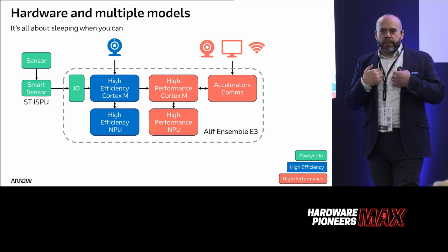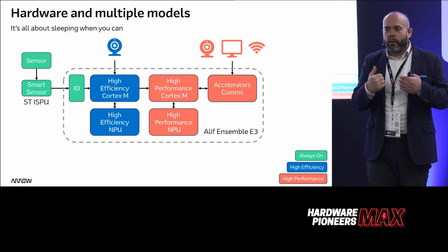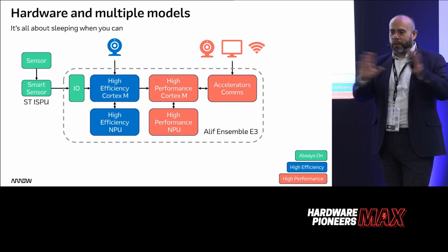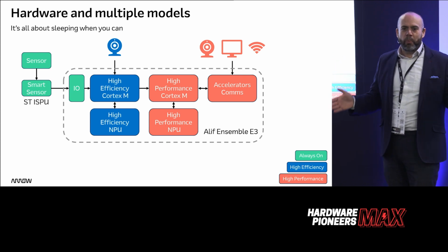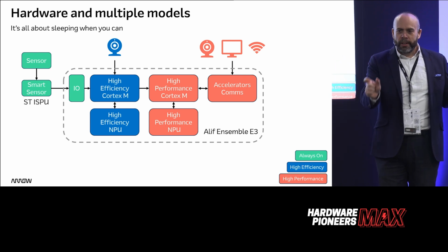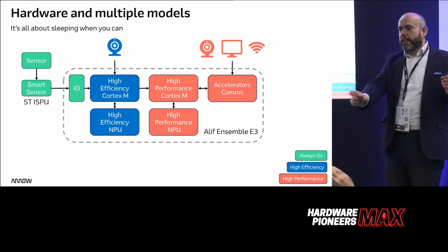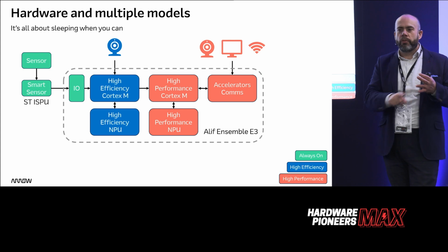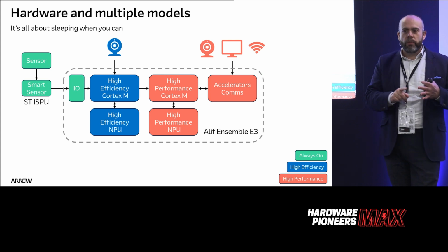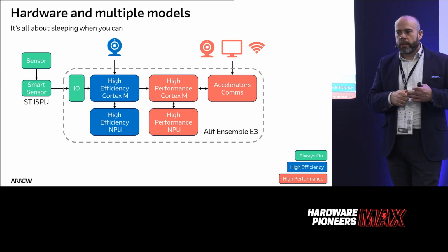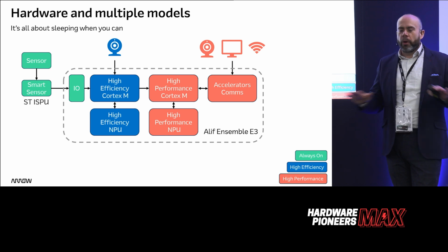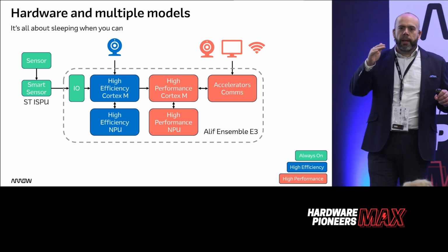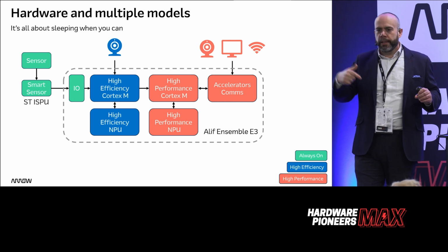I'm interested in processors. So for me, the processor is the most exciting part of any product. However, the people who are selling your product, your business is interested in the cost of your product. And believe it or not, the processor, the little gem of brilliance in the center, is not often the most expensive bit. And so if you can reduce the number of fans, if you can reduce the size of the inductors, if you can reduce the thickness of the cables, the BOM cost of your whole product comes down. So I would urge you, even if power isn't something that you think is important, it is.